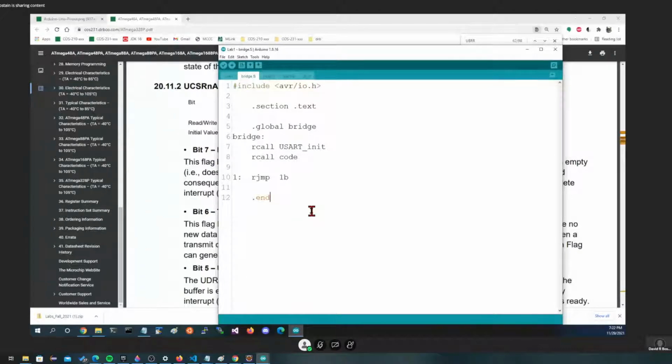When the reset occurs, it's imperative that the USART become reinitialized and that our code be started over. It's like rebooting. If you crash, you want it to reboot, but you don't want it to reboot and be writing your files to the network. You want to make sure everything is back to square one. So bridge takes care of getting us back to square one.